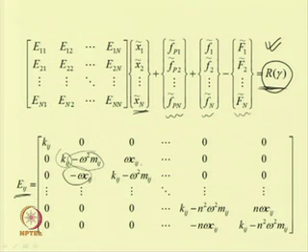So, here we have this damping term, then this is the K_ij minus omega square m_ij. For example, E11 will be equal to K11 minus omega square m11, C11 omega, K11 minus omega square m11. In that way, one can write this matrix. So, the E_ij terms will contain it this way.